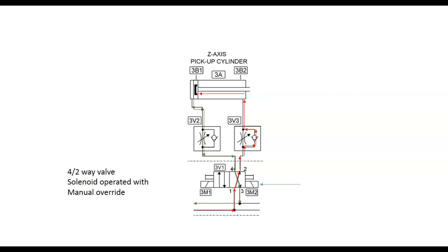So this is the way these things work, is that the way we do flow control, especially on flow control is hard to do on a single action cylinder. You have to meter in first of all, because the exhaust goes out the side of the cylinder, right? So what determines how fast it comes back is just whatever it does. But they're easier to control. But what we do, of course, we do meter out.